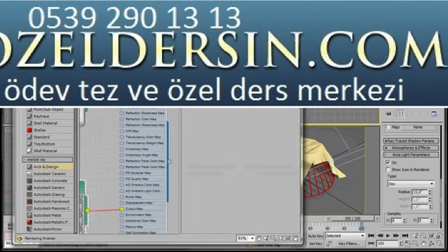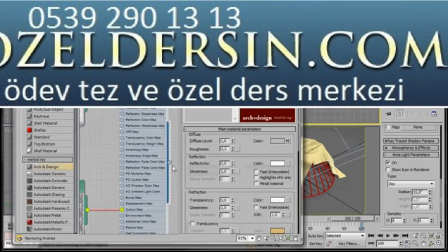Double click on the Arch and Design material to open it, and now we can drag the material over to our cloth. Just one more thing to do so we can see it is to go to the menu, and we'll click on Show Shaded Material in Viewport. Now we can close our material editor.